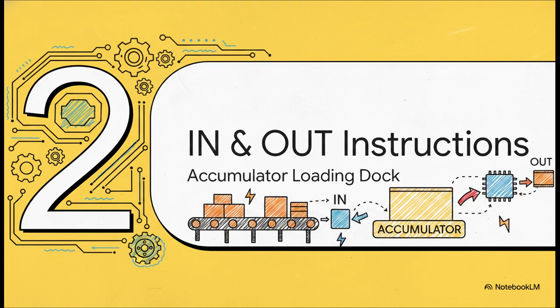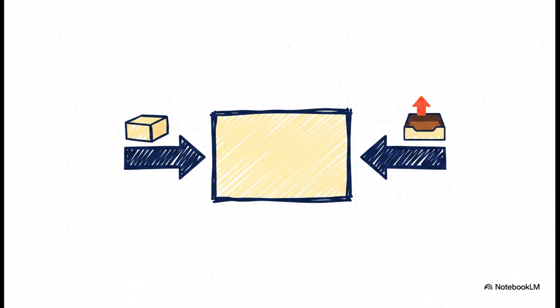Section 2. The IN and OUT instructions: the accumulator as a loading dock. Now, let's explore the core commands that essentially act as the shipping doors for our data flow. We've got two primary instructions here, IN and OUT. The IN instruction reads a byte or a word from a provided port directly into the accumulator. The OUT instruction does the exact reverse. It sends a byte or word from the accumulator out to a provided port.